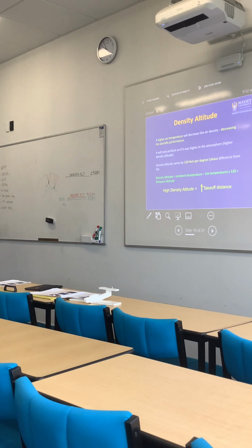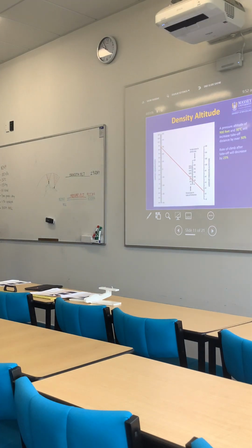there's also this little chart, which can be really useful to show you the effect of the temperature on your takeoff distance as well as your climb performance. So we've got the temperature up here, and we're saying for the example at Kofi Aerodrome it was 30 degrees, and we draw a line down, this red line here, to where it intersects the pressure altitude, and you calculated that was about 900 feet.